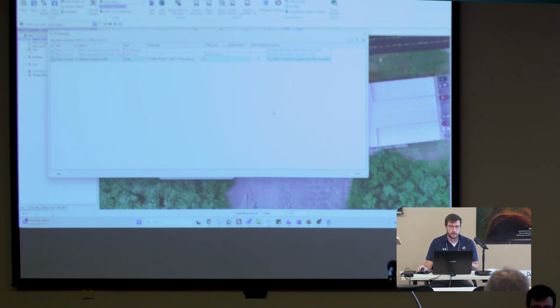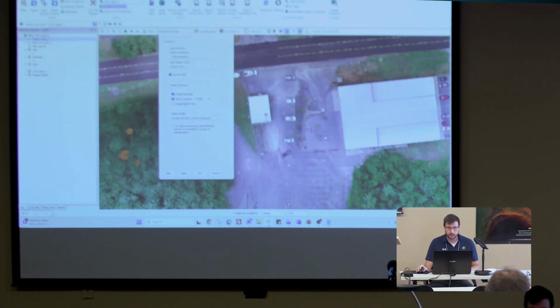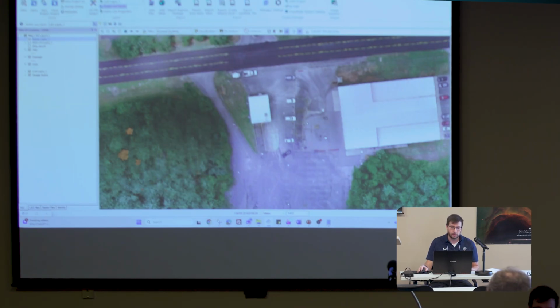If you add it to map, the data is not going to look correct because we don't perform on the fly reprojections, and it's just going to appear like the data is off in some weird spot. So if you do that, save the project, create a new project, and import that reprojected file you made, and then it'll show up in the right spot. All right, so I'm going to uncheck convert SRS, and I'm going to click OK here. The settings look the way I want.